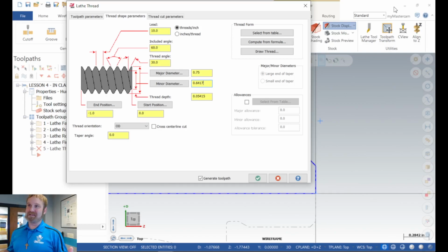The tap's either still good or it's not. I don't know why you bought the go and no-go gauge. Basically, if the no-go won't go, that means the tap's worn out. It's time to put a new tap in. You can't make radius adjustments on a tap, but it's all right. They were only like $60-something a piece.